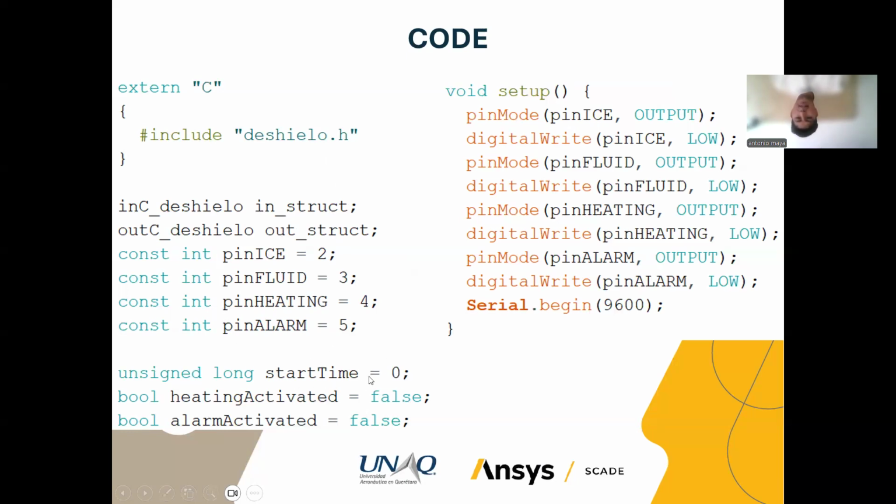And we have this time that is going to start counting when we have a signal. I'm going to explain this later, but this is a time that is going to be measured in ticks. The ticks are basically small pulses that are going to be counted by some function. There is a function in Arduino that can count the amount of ticks.